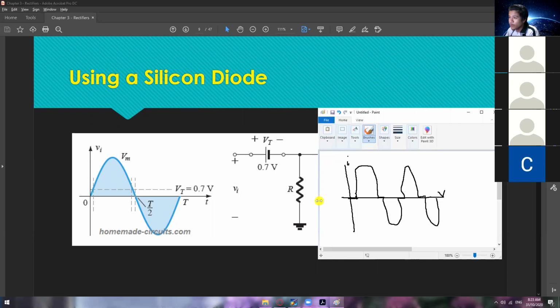So before, if we have 3 volts as our V peak, okay, so 1, 2, 3, you now have to deduct the 0.7 volts. So our VM, or V peak, now will become 2.3 volts.